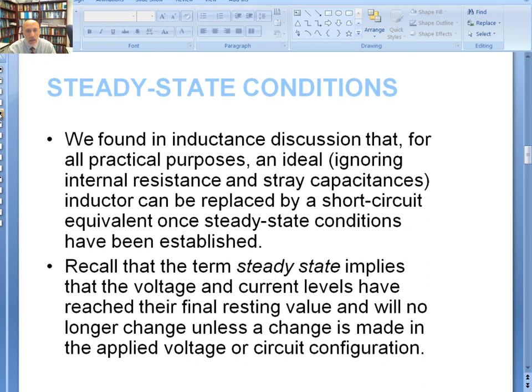The inductance does have what is called the reactance. The combination of a resistance and the reactance gives you what is called the impedance. The reactance of an inductance is a function of the frequency. It's equal to omega times L, where omega is the radian frequency, which is 2 pi f. So it does act against any frequency. If you're looking at the 60 hertz power coming out of the outlet, 2 pi times 60 is whatever that number comes out to be. You have to multiply by the inductance value. That product gives you the impedance, which is in ohms.